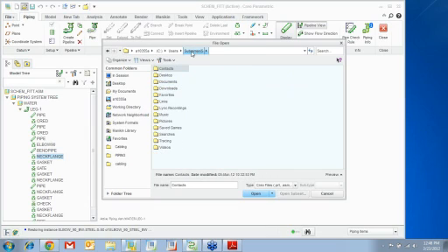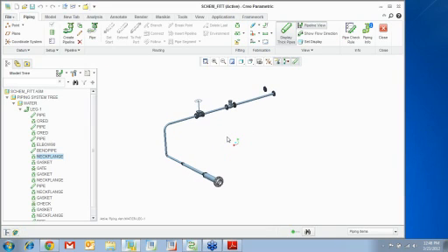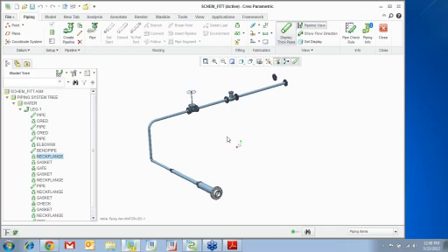I'm sorry about that, but yeah, you can actually create 2D drawings of this piping. It's just like a Pro E component, and you can also send this to a software called Alias Isogen, which will create the isometric drawings with the pipeline views and all the symbols with it. And you can do that from right here.